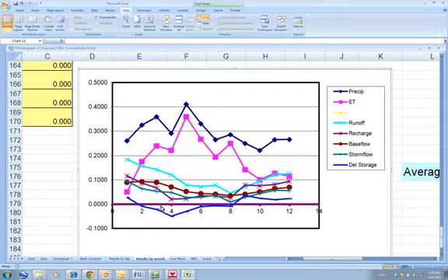And so what's happening is the aquifer is receiving this recharge, it's filling up, and as it fills up, the discharge out of it is increasing, but the max discharge is lagging behind, and the minimum discharge is also lagging behind the minimum amount of recharge. And so that seems right if we're changing the inputs to this large aquifer system. It seems like the outputs should lag behind by some characteristic time, and in this case, for this aquifer, it seems like it's a month or so.